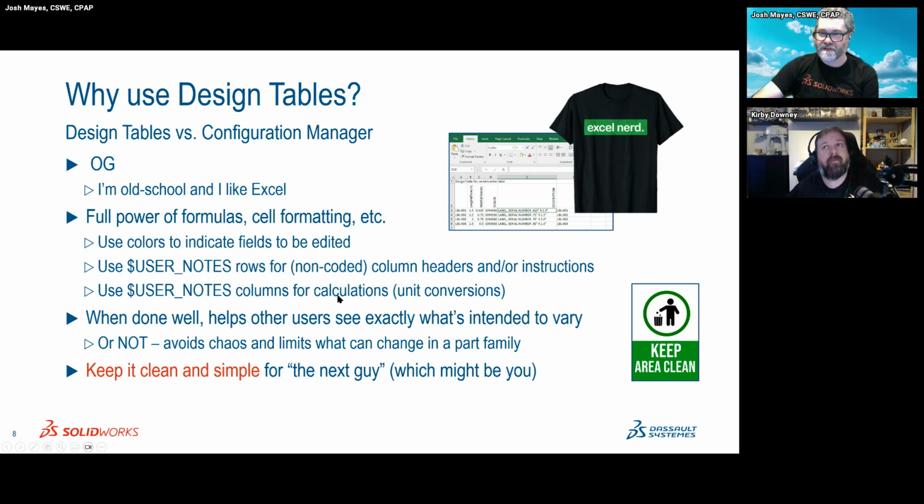Maybe your file is in inches, but your input dimensions are coming from the supplier, maybe you're tabulating a purchased component and all the dimensions are given to you in millimeters, but your design is in inches. You can actually input those values in the table in millimeters and have Excel do the unit conversion for you and drive the actual dimensions in a different unit. So we'll see that as well.